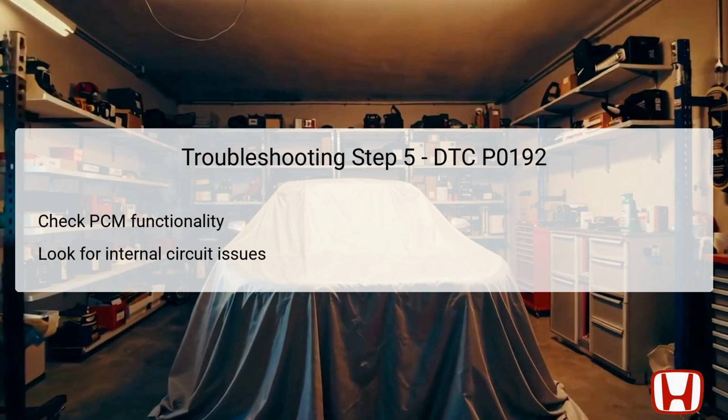If no issues are found with the PCM or the sensor, the technician may need to consider potential wiring issues or connector problems that could affect signal clarity. Ensuring that the PCM is correctly interpreting the information it receives is essential for the overall functionality of the vehicle's fuel management system, and repairing this component may be critical if it's identified as the source of the